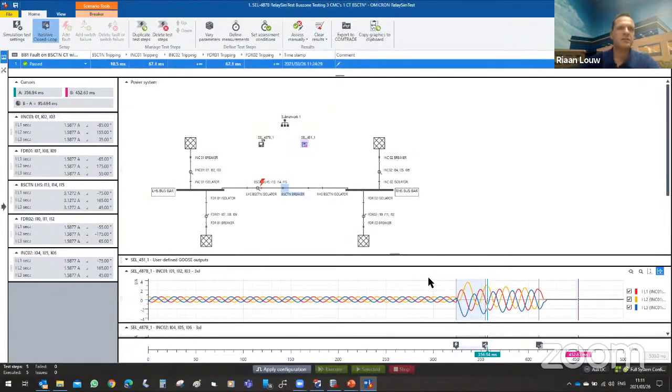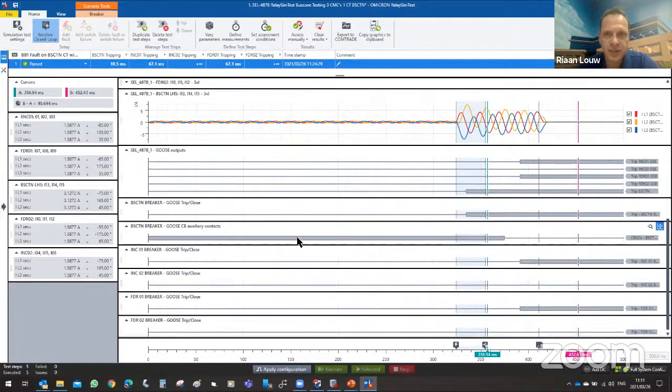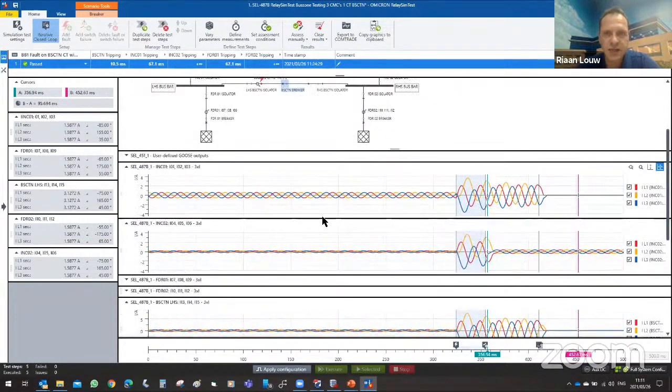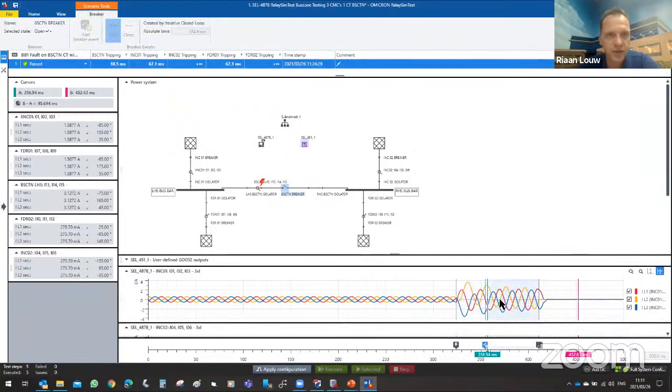Okay, so let's evaluate and assess what we are seeing here. In the first instance, I had all the bays seeing normal current flow. Again, don't pay too much attention to the size of the currents. It's just distributing it according to the scale. But then we can see when I have the actual fault condition, the section trip. This also agrees with my accelerated trip, so the section opened first.